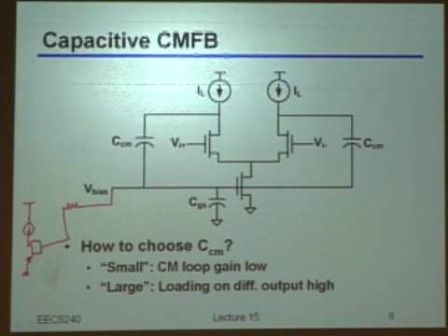We also like this scheme, as maybe Elad mentioned last time, because we are deciding to control only one spot, only the tail current, not the two different current sources on the top. Having only one spot to control is better than having two, because otherwise there might be some conversion from common mode to differential mode due to mismatches in the two paths that you control. Maybe you saw this last time. But anyway, this topology is also pretty easy to implement, simple to do.